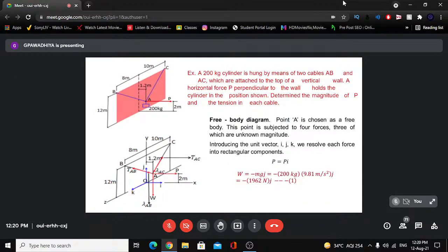Now we have to analyze this joint and find the tension in the cords, in these inextensible members, so that we can hold this weight in position as shown at A. So this geometry is stable at rest. The load is at rest. So first, we define all these forces.